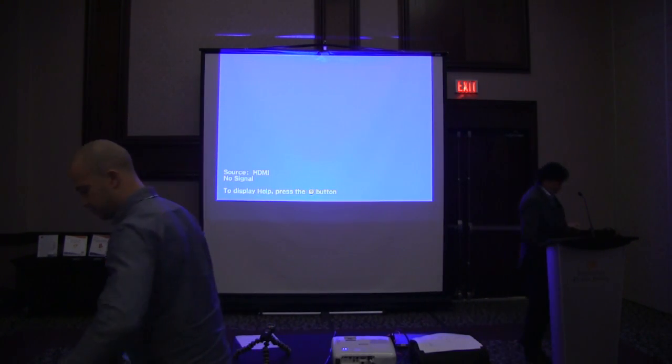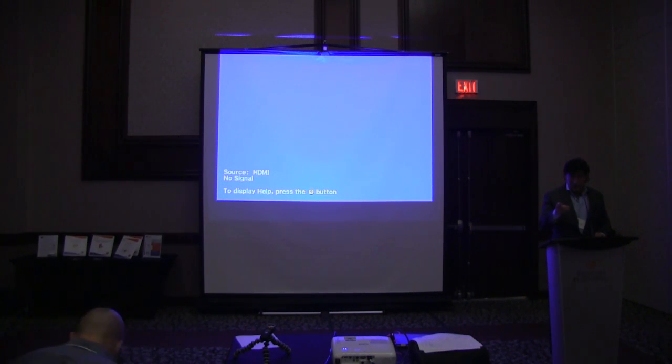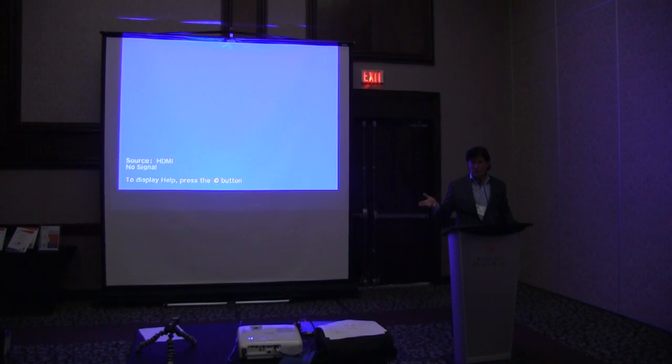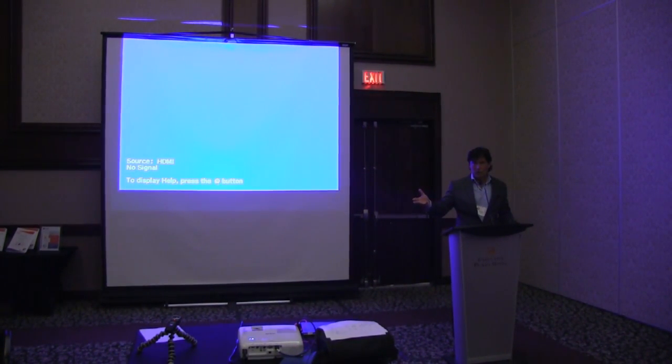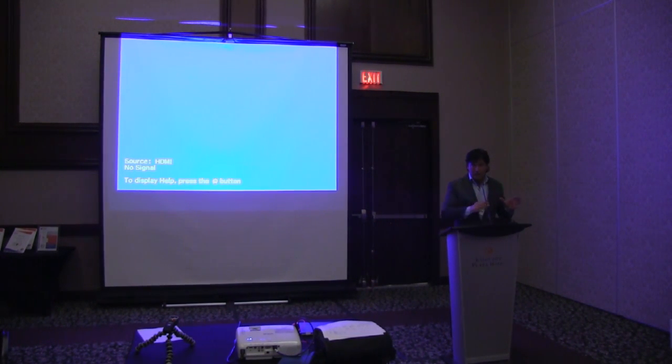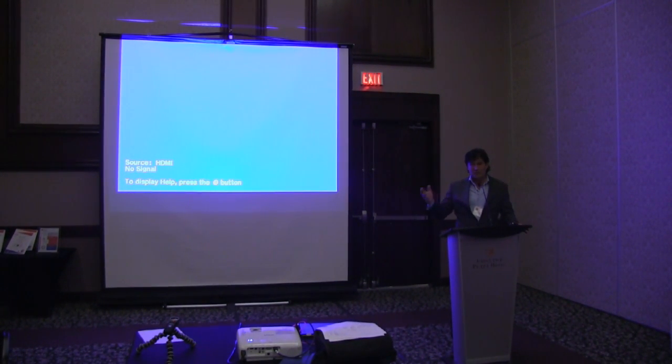Thank you very much. When it comes to that software, the question was asked, and we never answered it, about where are my CFMs. All I want to know is the CFMs. I've got to run CFMs to the room. 100% right. It's not a stretch from there now that we know BTUs per room to turn those into CFMs. That's where the existing duct design software will integrate. So we have this software sit on top of the existing duct design software, and it'll feed the BTUs to the duct design software, which is going to give the CFMs.